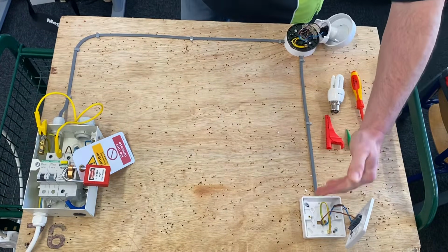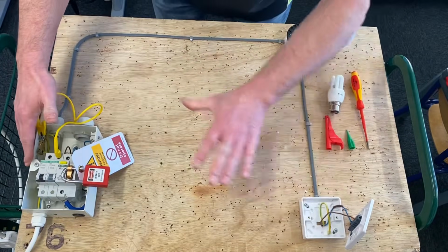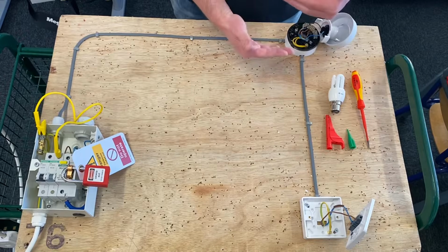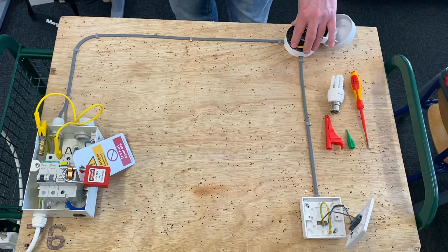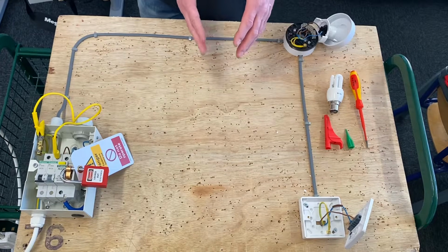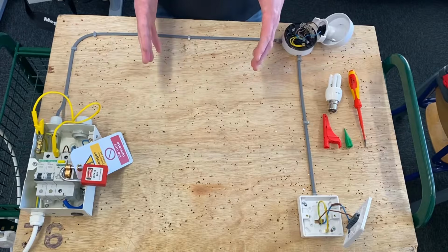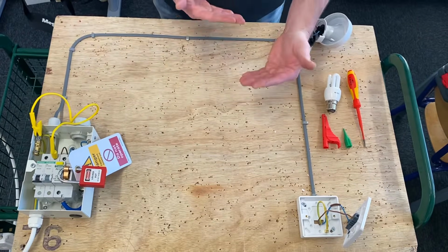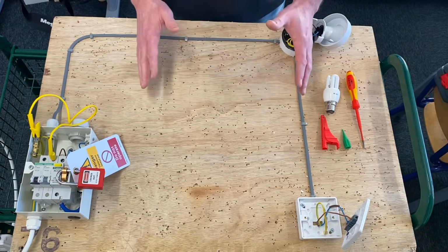However, in your own mind, you're thinking that this switch is further away from the consumer unit than the lighting point, which is true, but the amount of cable in circuit is longer when we measured it at the lighting point. However, I said to you at the start, whichever reading you get, which is the highest, is the one you record. Okay, we've used logic here to get our highest reading here. When you're in a full installation, you're going round, it's that highest reading achieved, wherever it is, that we would record.